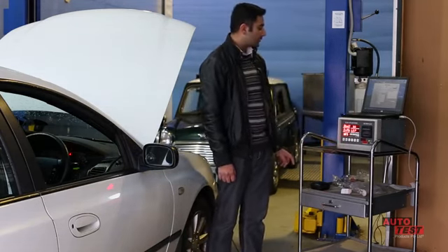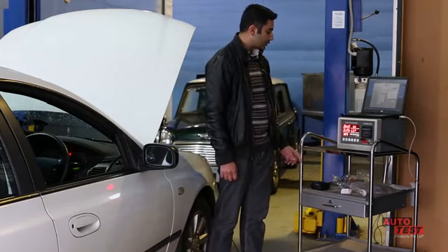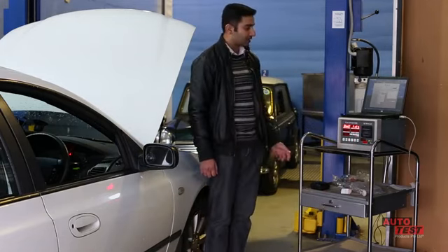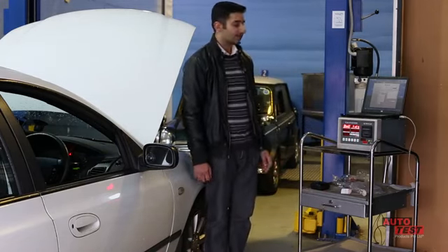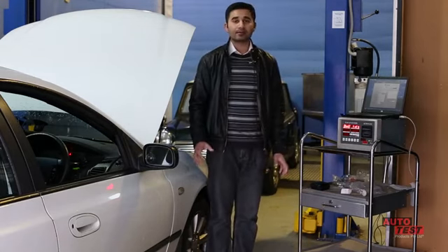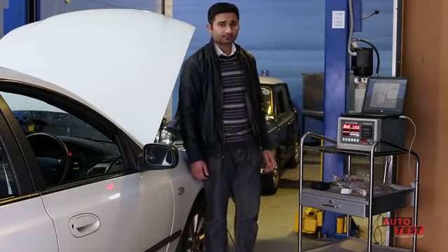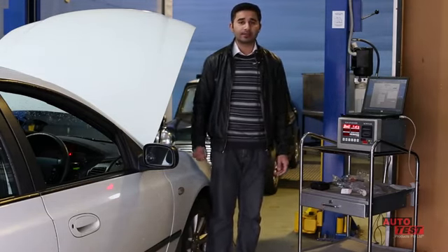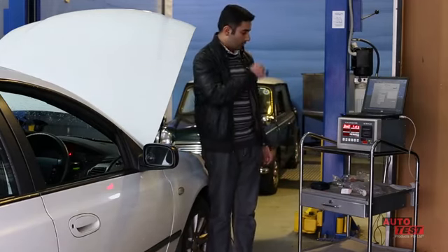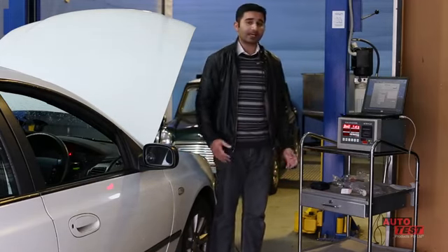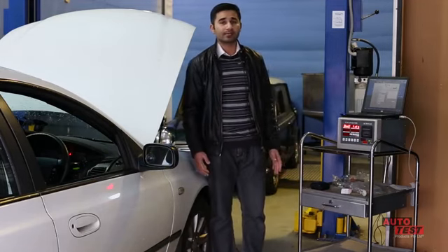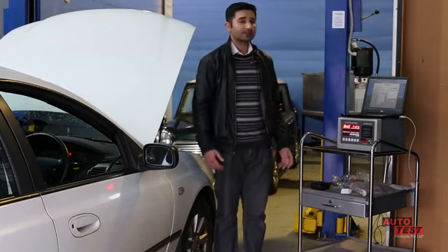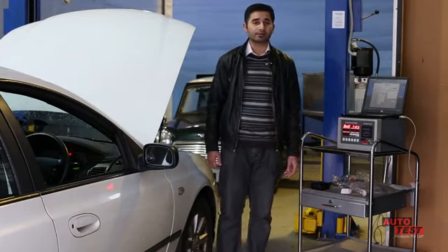It will prompt enable Bluetooth, yes or no. Select yes and then press OK. The screen now displays OBD2 initializing. While it's initializing, it's going to scan for Bluetooth devices. And then when it finds our OBD2 connector, which is connected to this vehicle, it will establish a connection. It may take up to 30 or 40 seconds for it to acquire that device and connect to it. But once it's connected, it will start to display its readings.